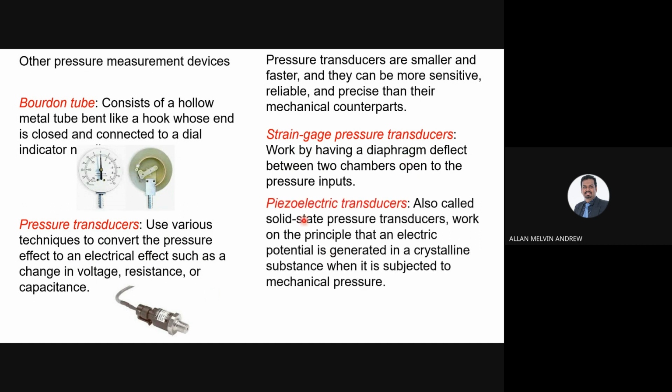Then we have piezoelectric transducers. We have a solid state, crystalline material inside, so it is also called a solid state pressure transducer. All these are pressure transducers. It works on the principle that electrical potential is generated in a crystalline substance when subjected to mechanical pressure.